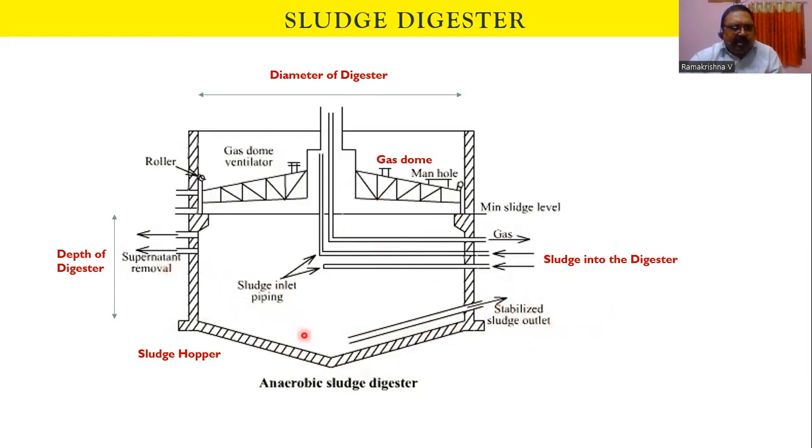In the sludge digester, the advantage is that digested sludge separates to the bottom of the conic hopper, and above it you have the raw sludge and seeded sludge at this layer, and then the liquid and solids are separated out. The liquid will go above this sludge mixer, and the gases released due to destruction of volatile solids will be pushed to the top.